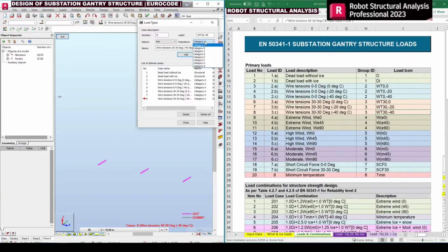So it is not a problem. Only for the automated load combination system as per Robot Structural Analysis do we need to define this carefully, based upon the European standard which is mentioned. In this case, as we are going to apply manual load combinations, we need not worry about this sub nature of the live load. So now we can apply the wind loads also.